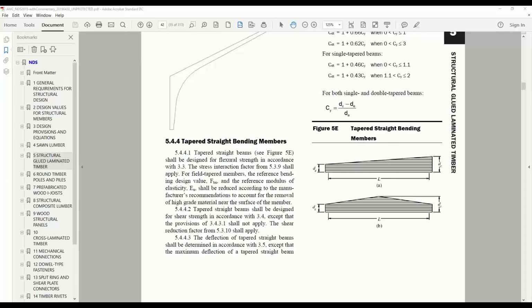But those are the two glues that we use. Excellent. There are other glues that are clear or white, but we just don't mess around. We've been using phenol resorcinol forever, so we found that it's really consistent. It works with the treatment types we have available. So that's what we stick with.